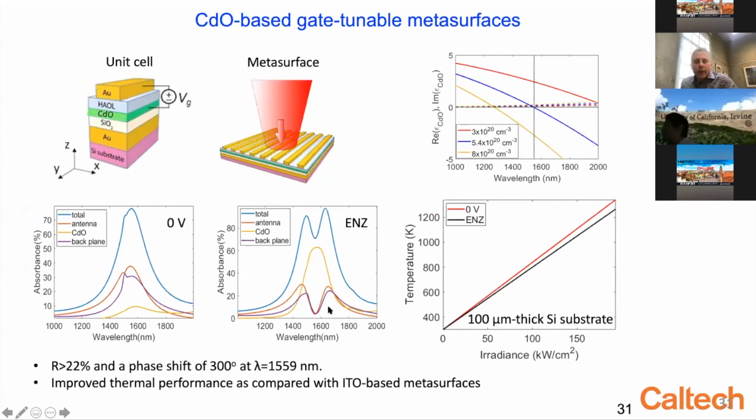So I could, in fact, mitigate this by going to a better material. I could use a material that has a higher mobility. And it's well known that one of the materials that has higher mobility than the typical transparent conducting oxides is cadmium oxide. And you can see here that the absorbance is still pretty high, but nonetheless sufficiently lower to be quite useful as an alternative to the other known conducting oxides. So I think this illustrates the power of materials design to improve the performance.